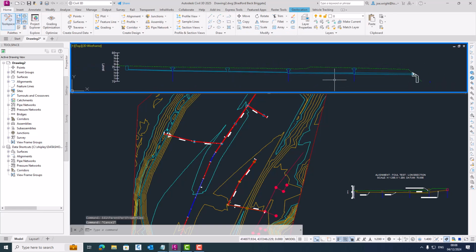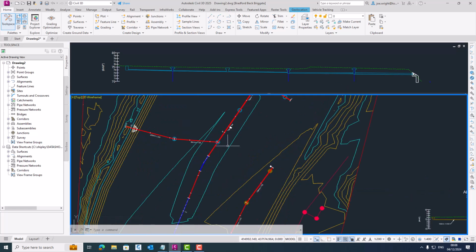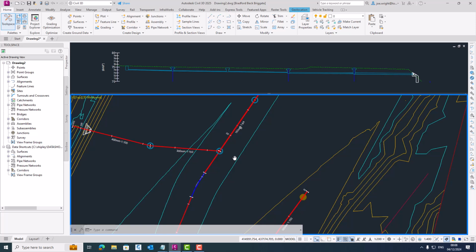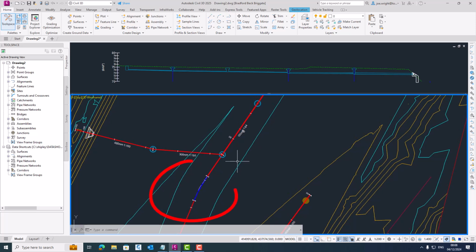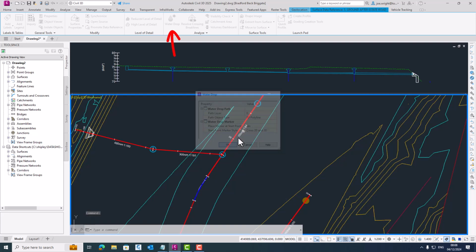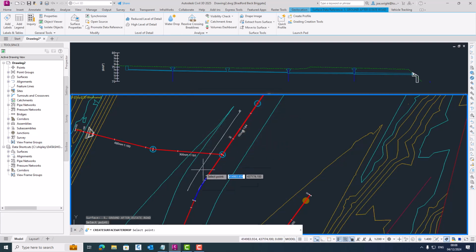And now we're going to get a couple of gullies into the correct position. The slope arrows will certainly help at this stage, but I can see from the contours approximately where the road is, and I know roughly the area where the low point is. So we're going to use the simplest tool in the box. That's this here, the water drop. Click water drop and then select where you wish to start, and it will draw a line to the drain point. So the end points here and now here